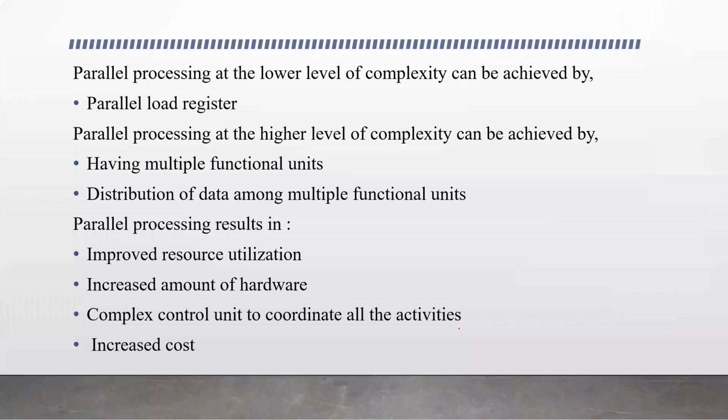Shift registers. We know shift registers are used to shift the data serially. If there are 4 bits that have to be transferred between registers A and B, the 4 bits are transmitted serially, having a single line, a single data bus, between the units A and B. This is serial transfer, where shift registers are used. First the 0 bit is transmitted, and once that is transmitted, the first bit, then the second bit, and then the third bit. This way the bits are transmitted in serial registers.